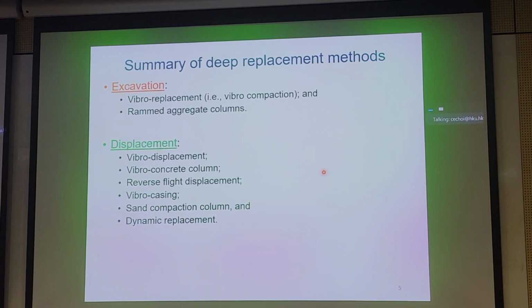And we'll go through each of these methods to impress upon you how they look, using videos if we can, and to give you just a mental snapshot of the wide options, the tools you have at your disposal if you choose to use deep replacement. Deep replacement is interesting in that if you use coarse granular material, it's almost reminiscent of installing drains in the ground, isn't it?